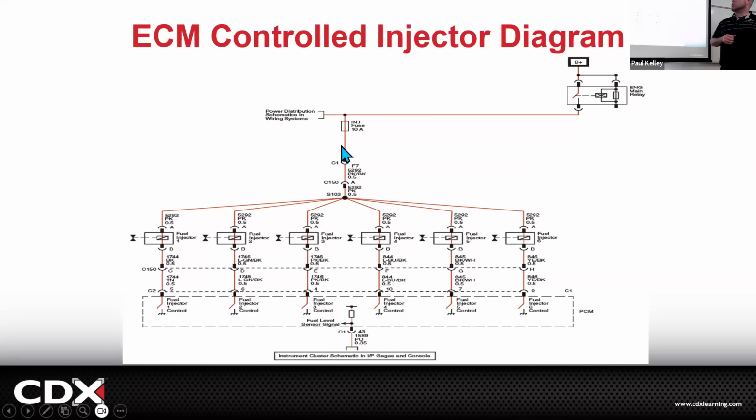What if the injector fuse was blown? What would we have? No injectors would work. That's not a misfire. That's a crank no start. Make sense? So if I roll up to the car, if it's a misfire, I'm not even checking that fuse.